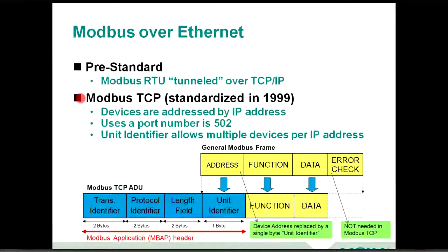Now, to go a little more specific into this, Modbus TCP means that now we address devices by IP address, which is their unique name on a network. If you've had some basic network training or experience, you know that to identify devices on your network, it's much like a phone system. If you were to call the main number for my office here at Moxa, our sales and marketing headquarters outside of Los Angeles, you might need to get to my desktop extension.